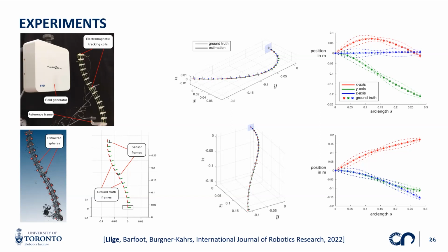Through the kinematics of the arm, it can compute where the laser scanner takes a point cloud, and then you can attach multiple point clouds into the resulting structure of the robot. From this point cloud we reconstructed the center line as ground truth, together with the pose. This laser scanner is quite accurate, so we use it as our ground truth to evaluate the quality of the state estimator. Does that answer your question?